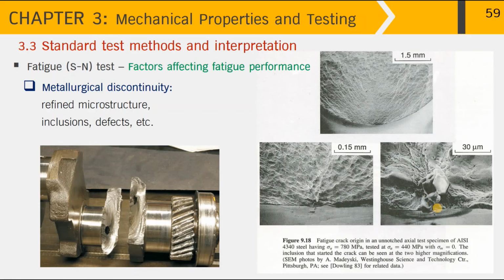So remember, the surface of the component is very important for fatigue performance. It has to be smooth, having high hardness and strength, with a good uniform and refined microstructure without inclusions or defects.